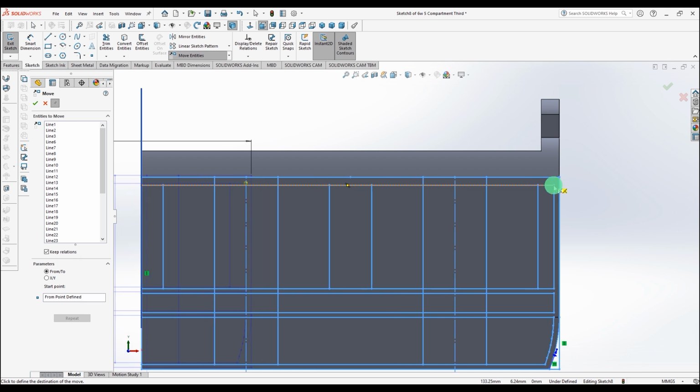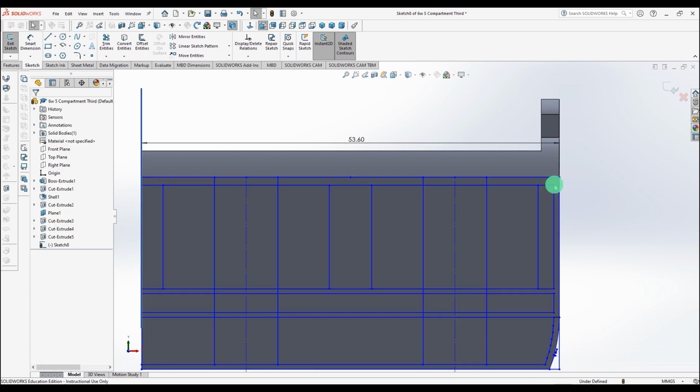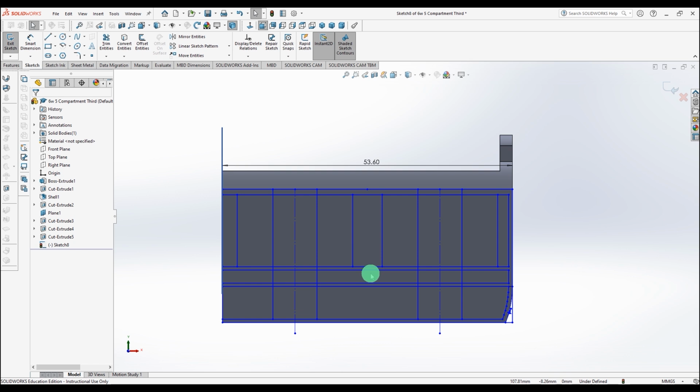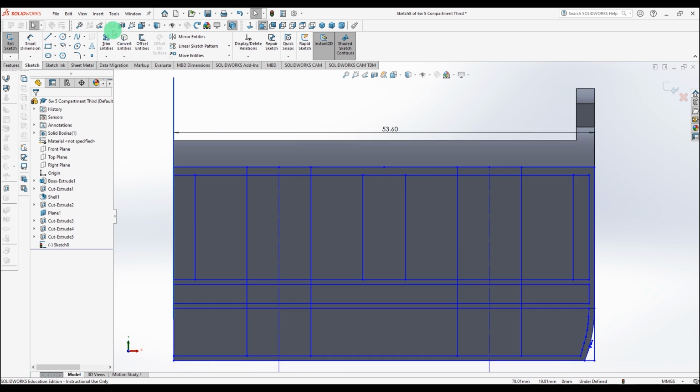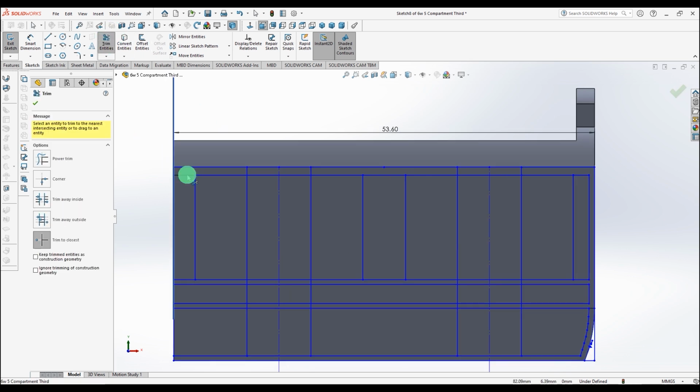So next task is to bring in the artwork that I prepared with all my two-dimensional geometry for the doors and the windows. And you can see I've pasted that onto a new work plane, or a new sketch, that I've created on the side of the coach, and I'm just deleting the bits and pieces that I don't need here to leave myself with the window apertures.